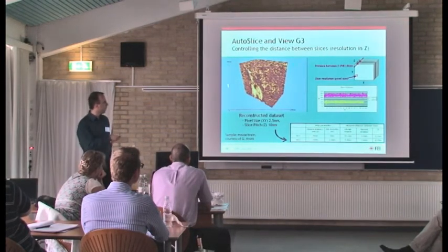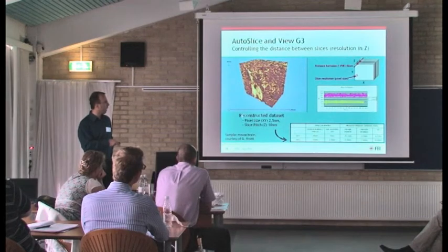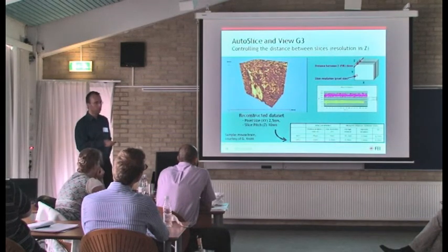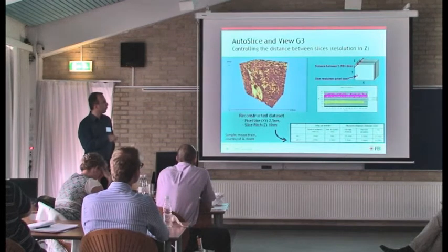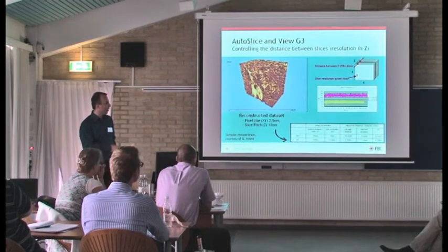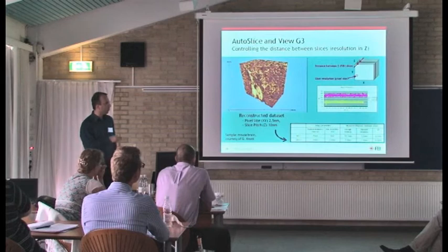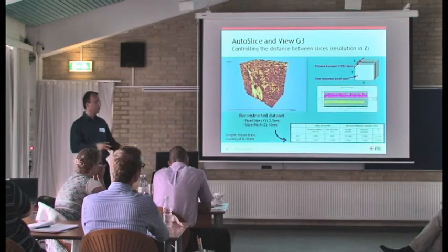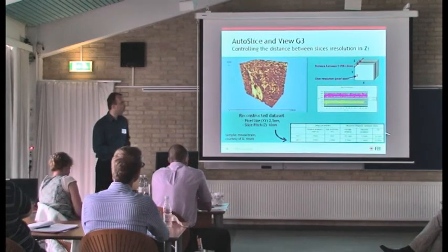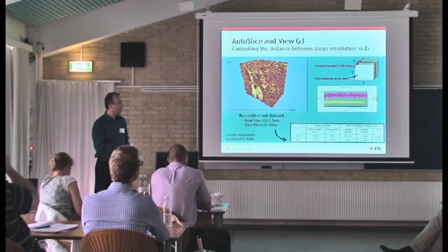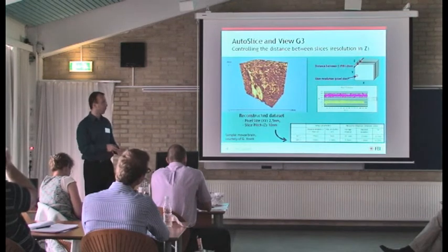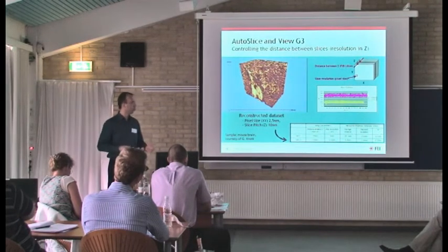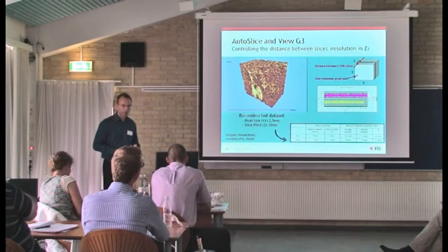If I take the data set which I have here, where I had a pixel size of 0.5 nanometer and a pitch in Z, so a distance between each slice, of 10 nanometer, I can really measure an average distance, which is a good match with what was actually targeted, as well as a way to measure the deviation, whether standard or 3 sigma. That's in line with the kind of metrology that one expects.